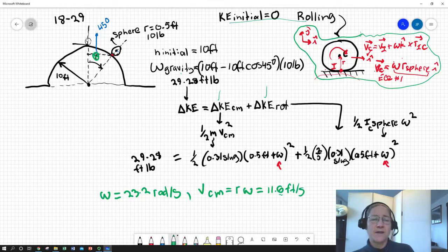But we certainly didn't have to go through as much intricacy of calculation as we would have if we had been representing gravity as a force that was resulting in a tangential acceleration of the center of mass and an alpha about the center of mass. We could have done that, obviously, and used our acceleration equations for a rolling body on a curved surface. We have derived that in our rigid body kinematics, but this was much easier because we only had to consider initial and final state.